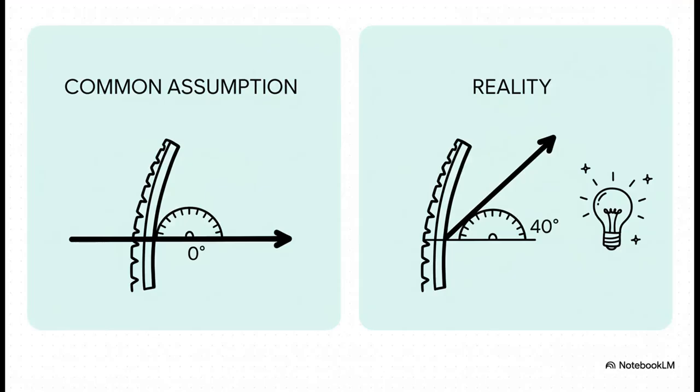Okay, get ready for another one that goes against everything you might have learned in class. We're always taught that for the best efficiency, the flow should enter perfectly parallel to the blades, right? Zero incidence. But here's the kicker. For inward flow radial turbines, actual research shows the sweet spot, the optimum angle for peak efficiency, can be as high as 30 or even 40 degrees. So if you're chasing that perfect zero incidence angle, you might actually be kneecapping your own design's performance.